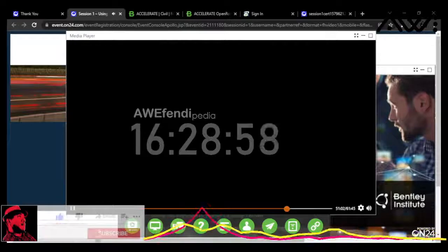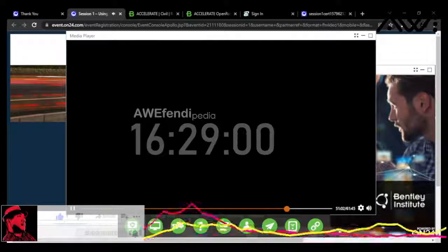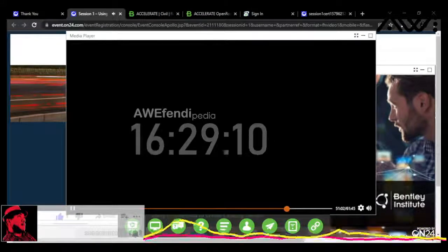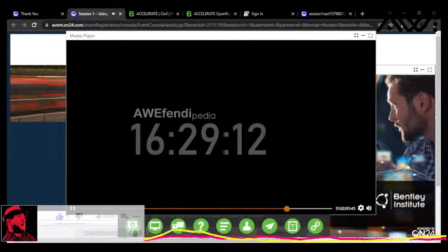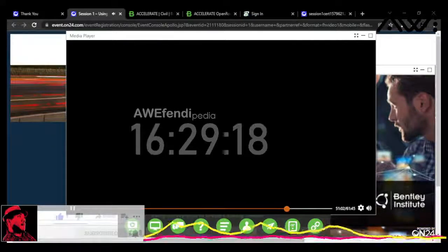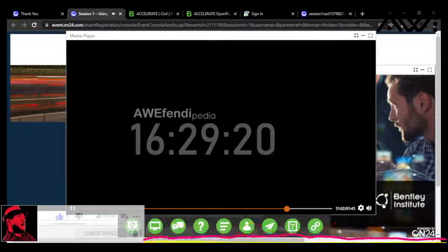You see those triangles go away. I do not want my bridge railings to be included in the terrain model, so I'm going to click on that and say do not include. So every feature that uses this feature definition will not be triangulated to. My bridge piers, those intermediate piers, I do not want those included in the terrain model. I'm going to set those to do not include as well. And you can see that cleaned it up pretty good.